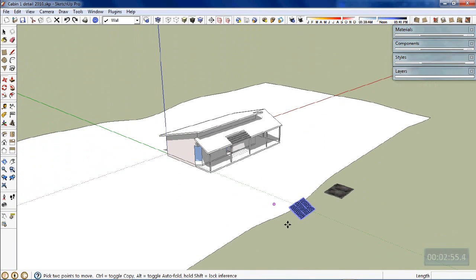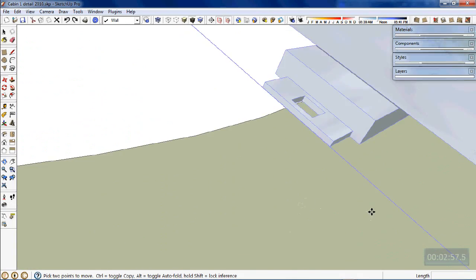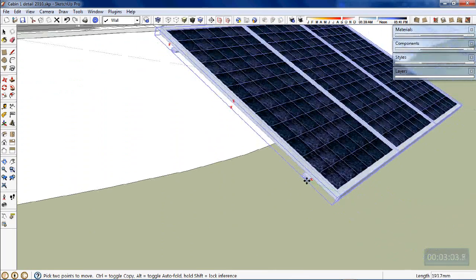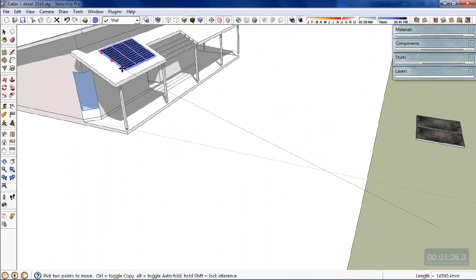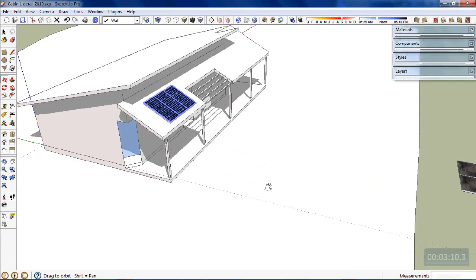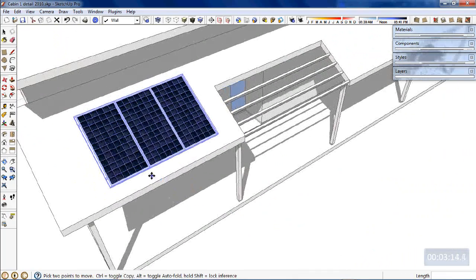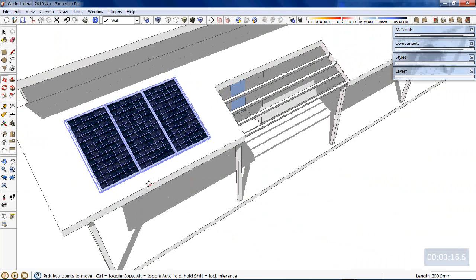Moving it from that endpoint, and I'll move that endpoint to somewhere up here. I think it says on face. Okay, that's better. So that's how it should have worked. It might not be in the right position here now, so I could move it along this fascia edge through here. Like I say, you could use tape measure tool to set it out.